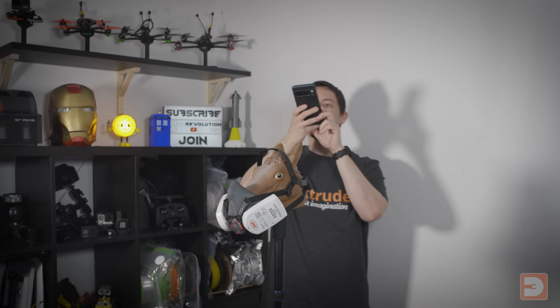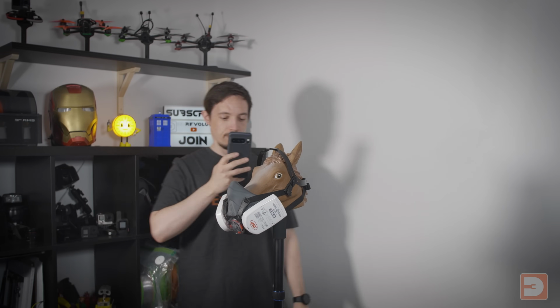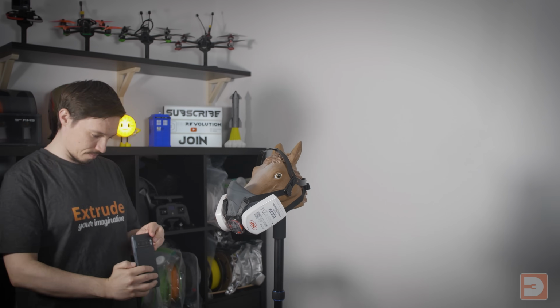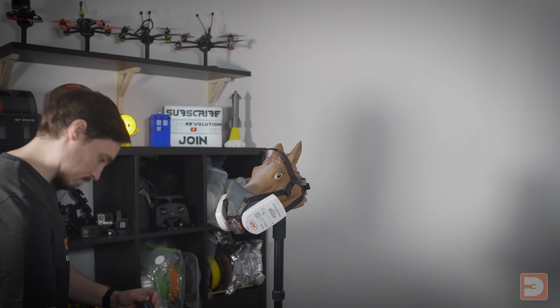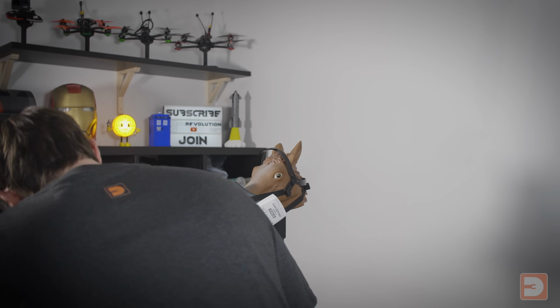Sort of similar to photogrammetry, where you take photos of an object from every angle and run it through an algorithm which then finds matching points from different photos and creates a point cloud. With a NeRF, you record a video of an object. You want to record 3 to 4 loops around your object, adjusting the height and angle of the camera on each rotation to make sure that you've looked at every side of your object from every angle.